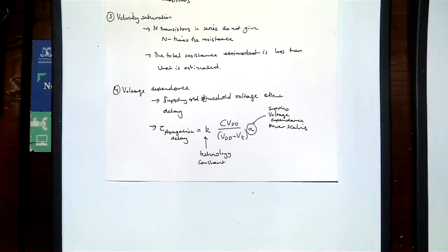So that linear propagation model doesn't necessarily hold. What you would need to do is calculate those propagation delays for a particular voltage, rather than saying, oh, if my voltage was this, I would get this propagation delay if I scaled the voltage by 25% or 30% down, all right?